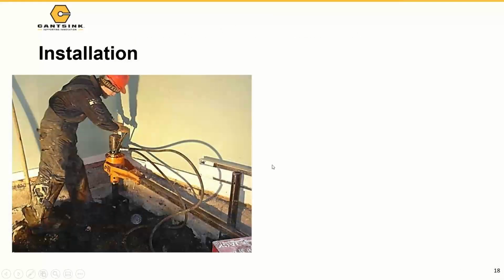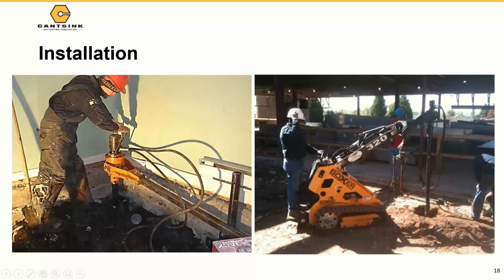Now I have some photos to show you. Whenever you see an existing structure, that means this is for remediation, this is for underpinning. They are putting this pile in to underpin that structure. The same thing over here. One of the things you see is how small the equipment is, even in the tight space over there. You won't be using a driven pile over here.